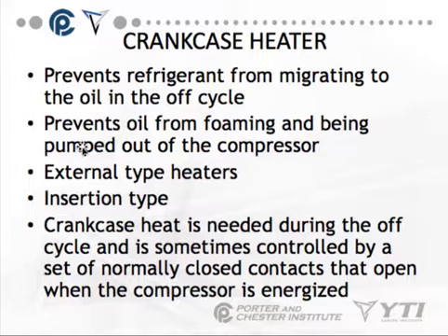Crankcase heat is needed during off cycle and is sometimes controlled by a set of normally closed contacts that open when the compressor is energized. If you look at a contactor in some of the bigger systems, you'll see an extra connection on the back of the contactor itself. It's normally closed. That's why you always check with a voltmeter to see what is energized, even if the compressor is not running. So all of these that we've talked about are additional components that you may or may not find on the average refrigeration system. Okay, you have your four basic components and then you just build from there.